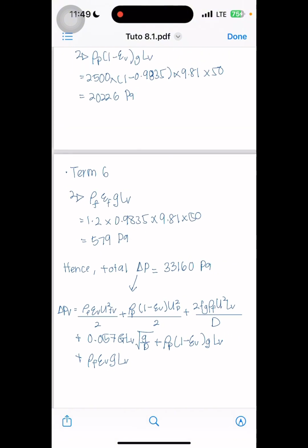I would like to mention that the available blower pressure at this maximum flow rate is 0.3 bar, so the lift line will not operate as required. Reducing the gas velocity safety margin will not help, since this will cause the line pressure loss to increase.